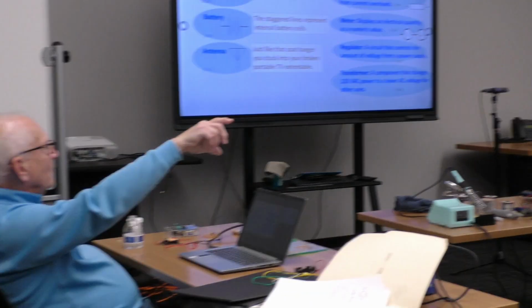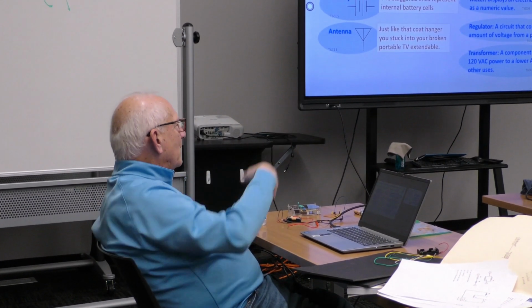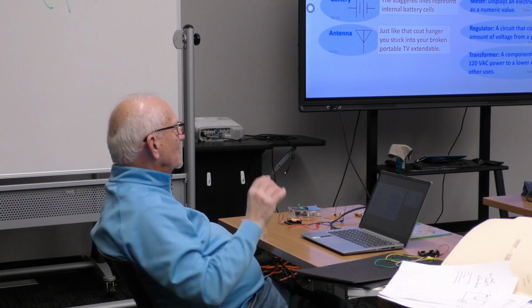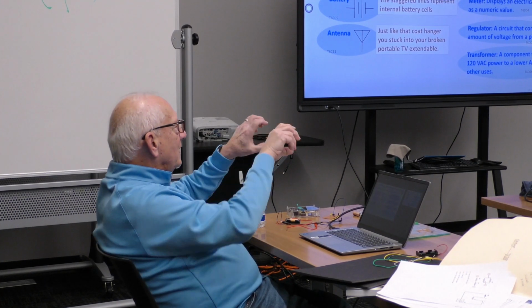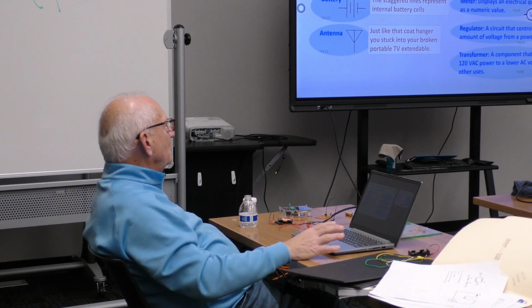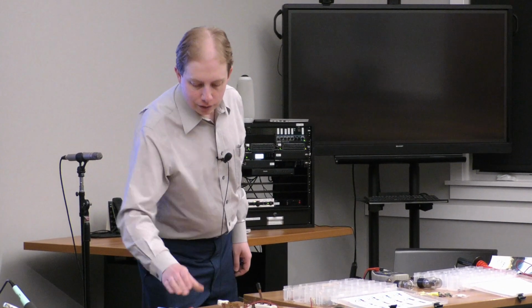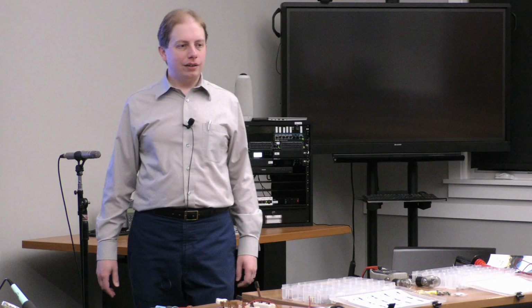Sometimes you'll even have taps in a transformer. So going back to Nelson's tube example, you might have a filament voltage of 6 volts or something, but then you may have a higher voltage for other aspects of the circuit or the tubes. And so there's multiple connections, and similarly, multiple numbers of wraps that you tap off of to get the voltage you want. Okay. Yep. Oh yeah, so you'll see one of these, they might have 12 wires sticking out of it, and each of them corresponds to that. Yeah, and usually they're color-coded, but I hope you have the data sheet that came with it, or it's hard to tell what's what.